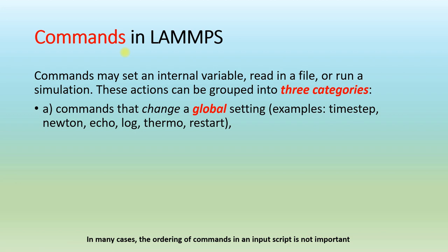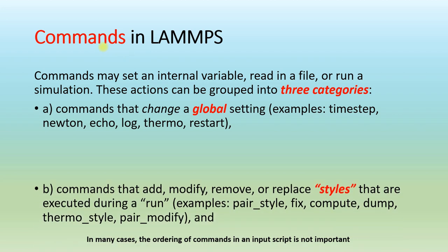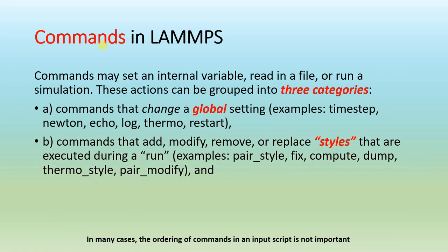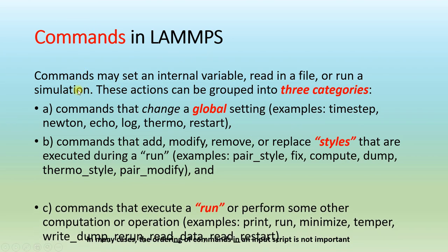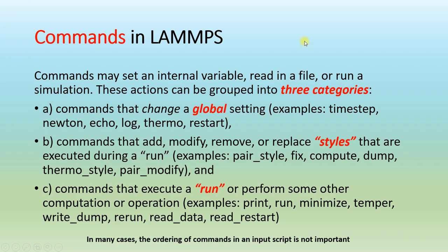The second important group of commands is those that add, modify, remove, or replace styles. These are generally called style commands that execute a run. For example, there are pair_style, fix, and compute commands. And the third category is commands that perform some other computation or operation. For example, the print command prints something on screen or to a file. Another example can be the minimize or run command.